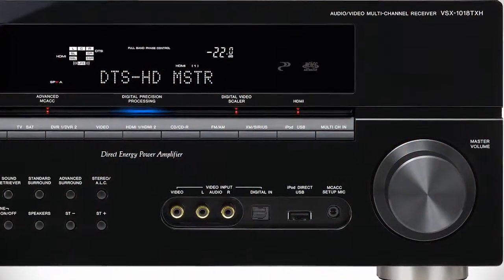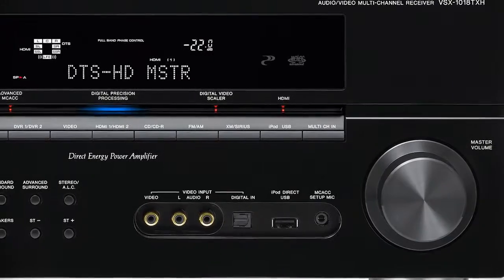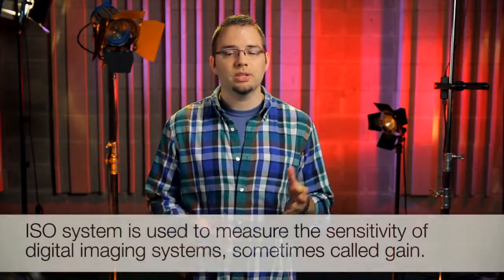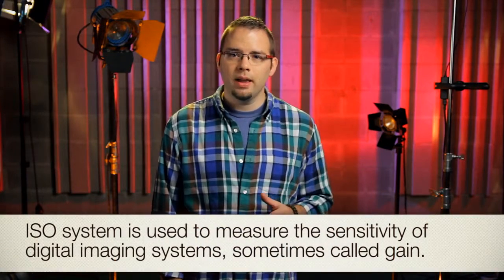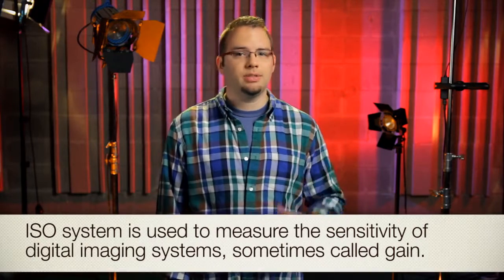The last thing in a camera system that affects exposure is the sensor itself. You can think about this like the volume on your stereo, but in a camera system, it's called gain or ISO. All image sensors have a range of sensitivities they can be set to in order to properly expose the image. Just like your stereo, the more you turn it up, the more noise is introduced into the audio. The more your sensor is turned up, the more noise is added to the image, and somewhat decreases the detail and dynamic range. So let's review.